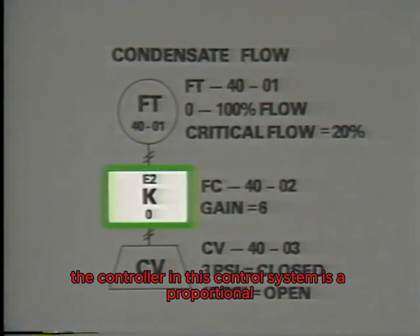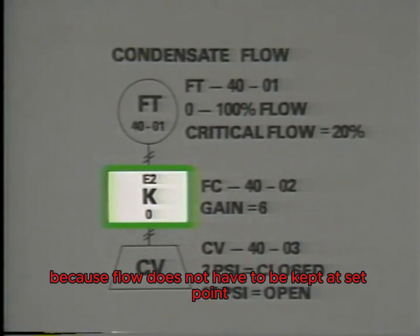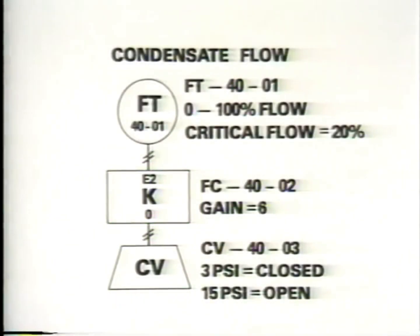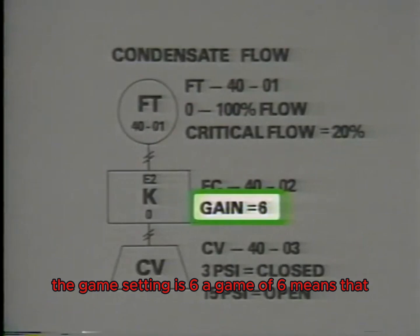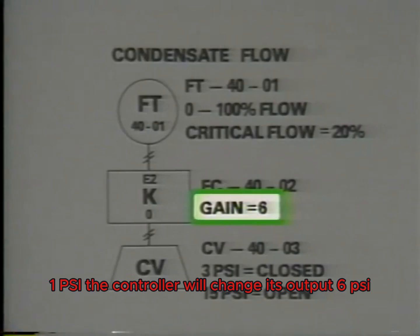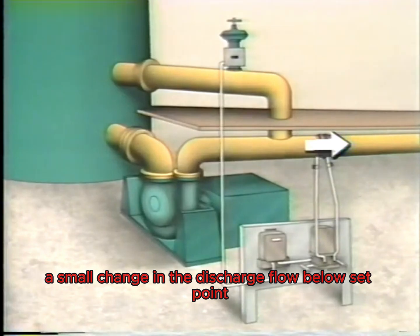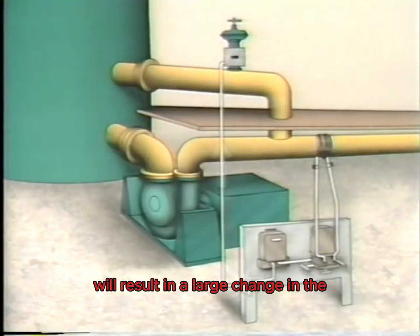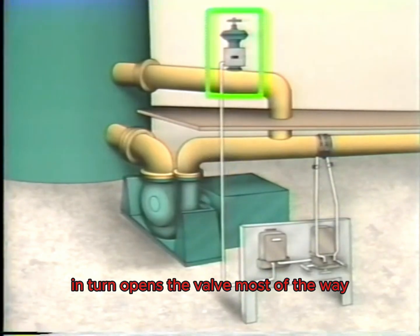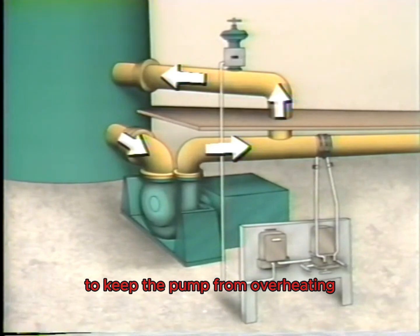The controller in this control system is a proportional-only controller. Integral is not needed because flow does not have to be kept at set point, only above set point. The gain setting is 6. A gain of 6 means that when the input to the controller changes 1 psi, the controller will change its output 6 psi. So a small change in the discharge flow below set point will result in a large change in the controller output. This in turn opens the valve most of the way and ensures that the flow through the pump is more than enough to keep the pump from overheating.